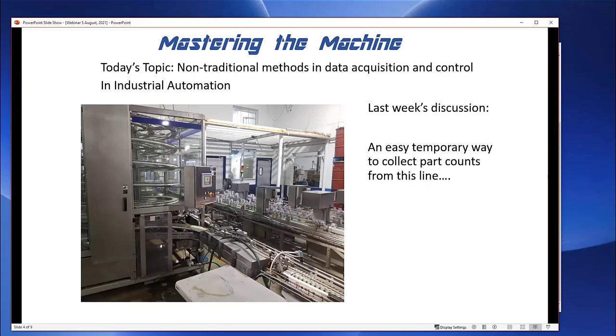But the thing that has stopped me from doing this is a series of events. We had a couple of, for those who are familiar with them, Allen Bradley Point IO modules, and we installed 2 of those on the line. And then I went in last week and I said, well, I'm going to add these to the PLCs. Well, lo and behold, I looked at the firmware of it, and it was a version C. And I tried to add it into the system, and the PLCs only allowed versions A and B. So I did something called disable keying, and I actually talked to Vlad Romanoff, who I don't think is on here, but got some advice from him.